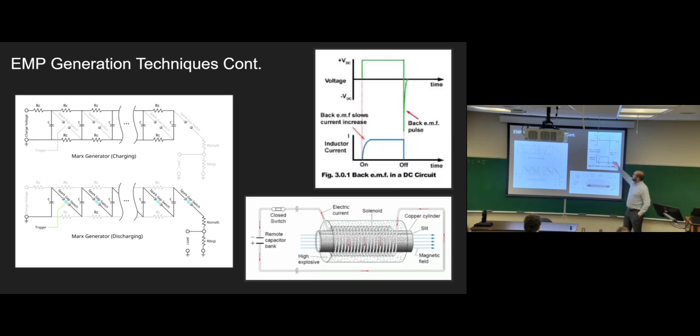But what happens here, we talked about the inductor. When you have current flowing through the inductor here, you turn it on and your voltage goes up. And then you go steady state and it goes there. But when you switch it off really fast, which is shown, this was a steady climb, but this is a fast turn off, you have what's called back EMF. And you notice that the magnitude of this back EMF is drastically higher.